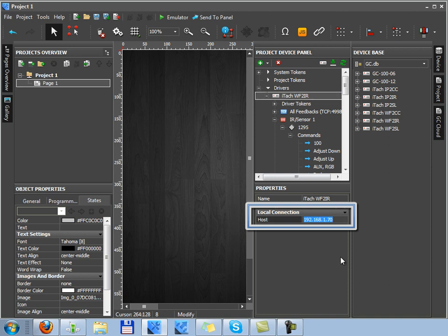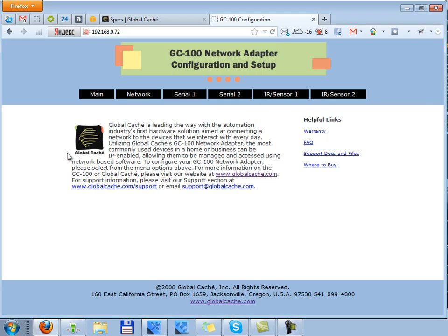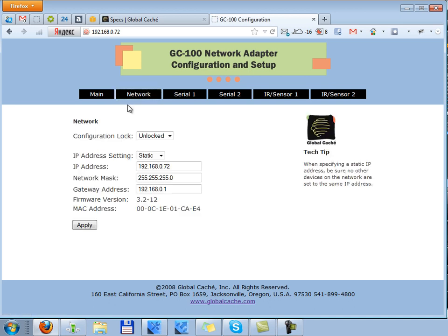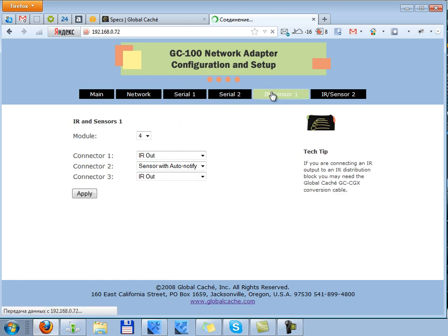In this case, you have to write the IP address of this converter in the settings of the ready Global Cache module in iRidium. Default settings of iTach can differ from those you need when working with your local net. That's why you have to set up your iTach device with the help of the web interface of Global Cache devices. There you can write the IP address of your device and set up properties of IR outputs.